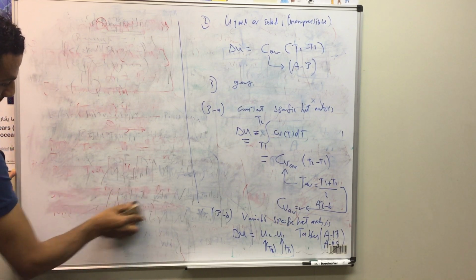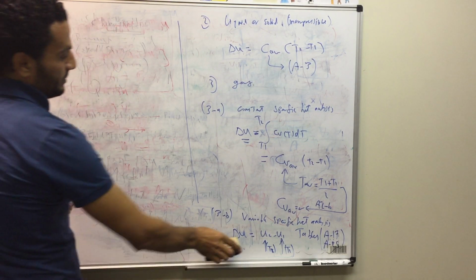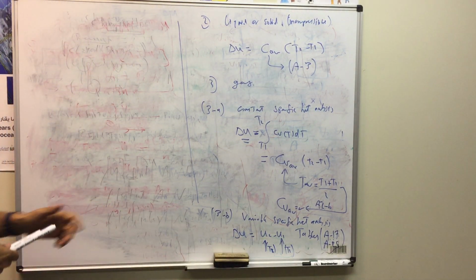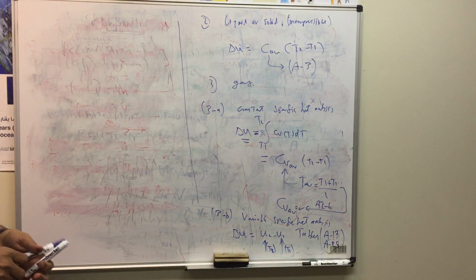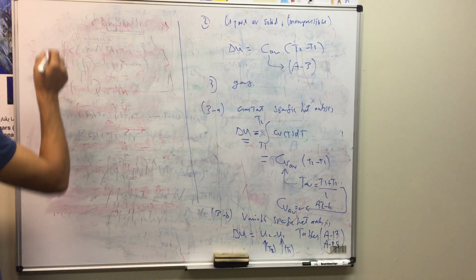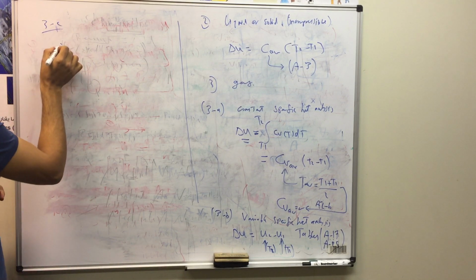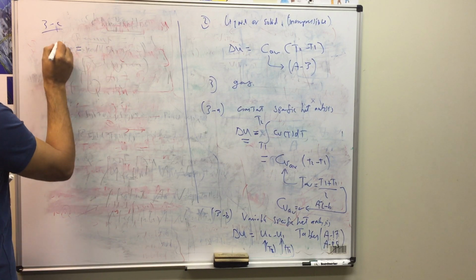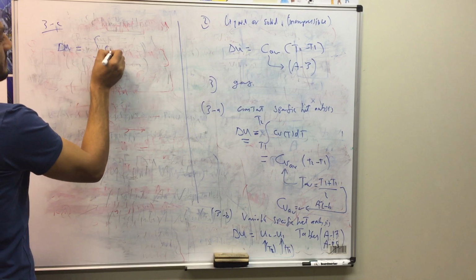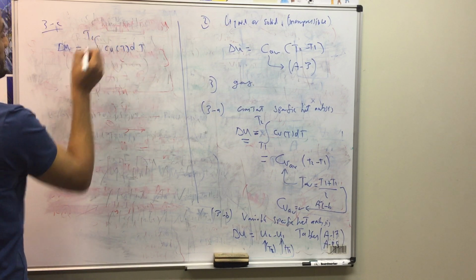But actually this case may not come to your exam because it's a time consuming case. So he will be asking you either to follow constant specific heat analysis or variable specific heat analysis. But let's just write it down, maybe for your knowledge, case 3C. In this case, delta U will equal the integration of Cv as a function of temperature dT from T1 up to T2.